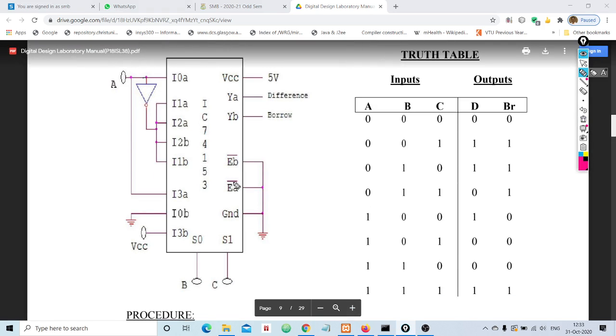So this is our multiplexer, and can you see, this is multiplexer A as well as this multiplexer B. These two are input values for B and these two for A. Enable pins, ground pin. What are these two? These are nothing but selection lines, where we are supplying the inputs B and C, and this is one of the very important input signals called A, because we have designed this full subtractor based on this input signal only. That's why it is A here.